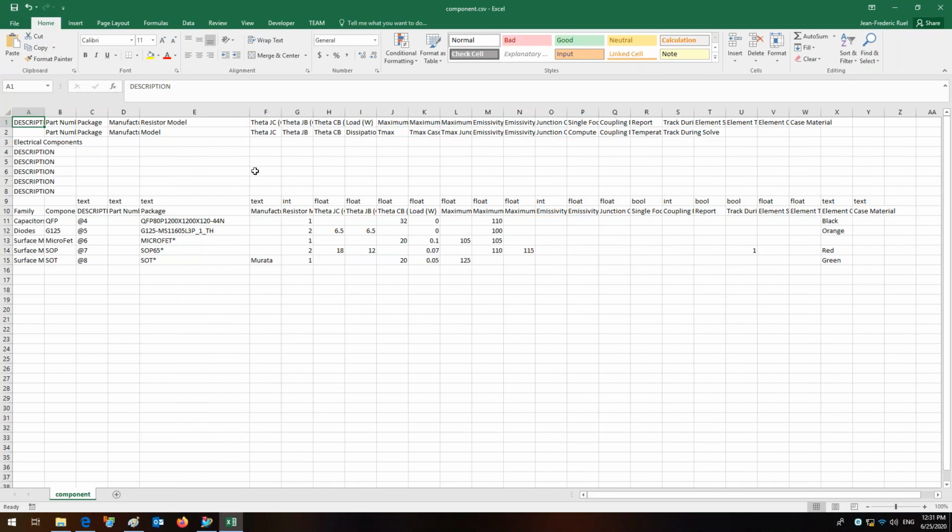As Yannick mentioned, this component thermal database is the matching between the electrical component in the ECAD system and these thermal properties, which are all based on either the package name, part number, or reference designator, even if it's for a specific board design. In our case here, we have the package being our reference.